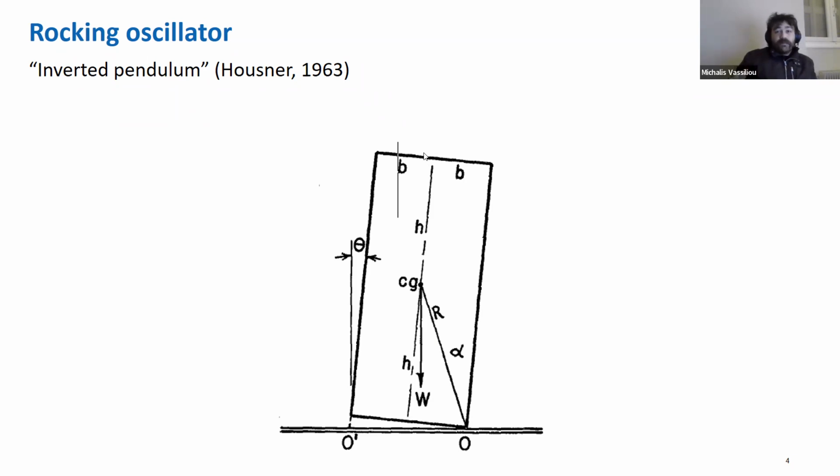The question is, if I take 100 ground motions that are horizontal and 100 ground motions that have a vertical component as well, statistically, do these two different sets create any statistically important difference? And the answer is that overall, no. The physical reason being that this lever arm is smaller than this one. Plus, overall, the vertical component of the ground motion is usually weaker than the horizontal. Plus, it is more high frequency. And frequency is very important in rocking because you need persistence. You need to be pushing for a long time.